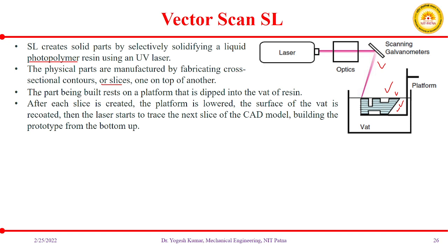For this, the part being built rests on a platform, which is dipped into the vat of resin. After each slice is created, the platform is lowered.